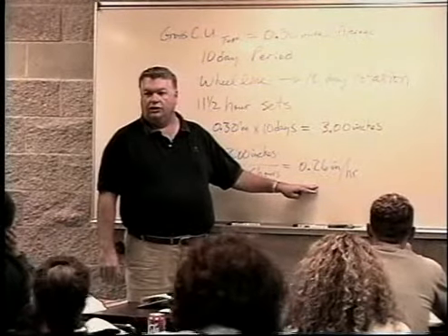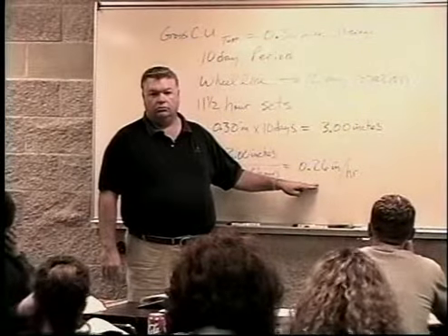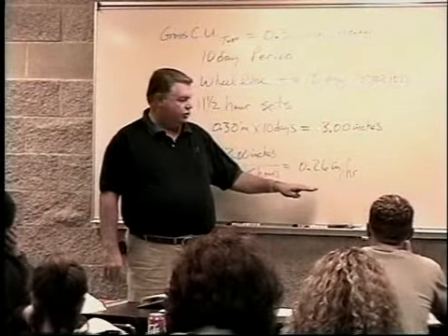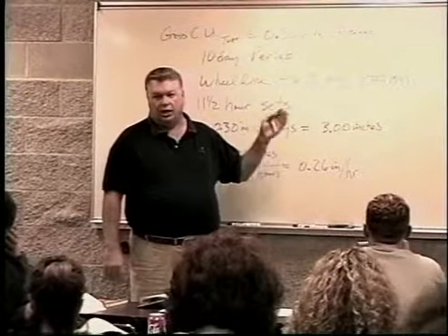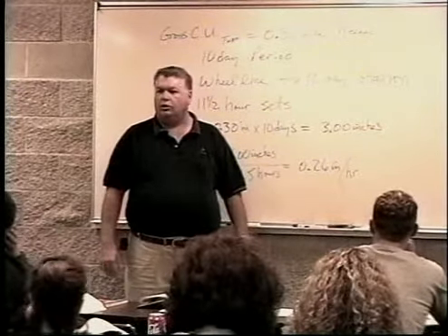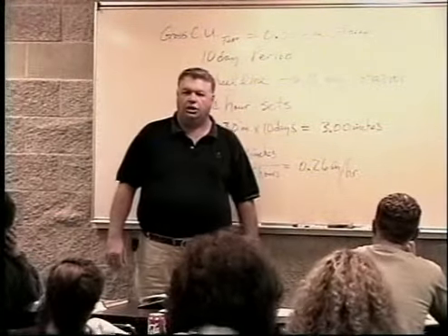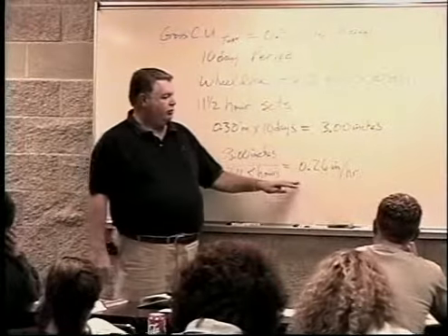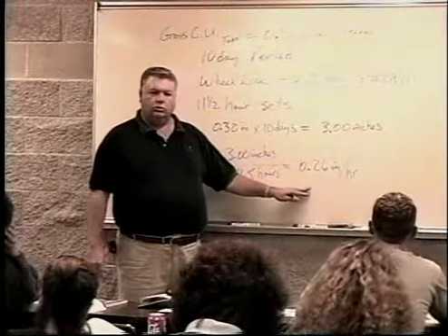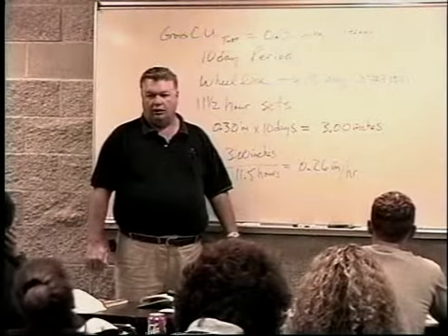You know, if we have a heavy clay soil, this may not cut the mustard. But if it's a silt loam up through the sands, your intake rates will probably be fine at 0.26 of an inch per hour. But you must check your soil characteristic intake rate to make sure that your system can produce the amount of water and make sure the soil can handle that amount of water.